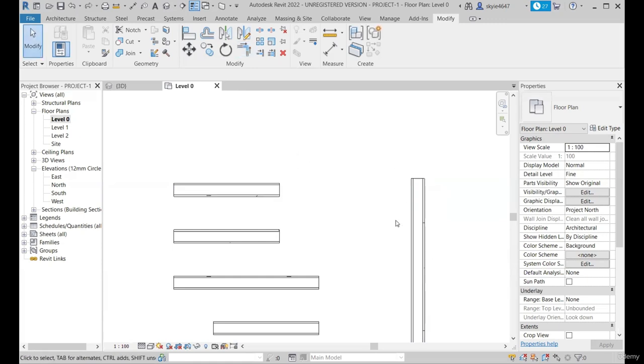So if I select the second element, you can see the corner is trimmed like this. I Control Z it again, and I will just extend this wall further beyond. Using trim extend can be a bit confusing, because it depends on which side of the center line of the first element you select. If I choose this wall initially and hover my mouse over the upper part of this wall, which is above the center line of the selected wall, you can see the dotted line terminating wherever the selected wall's center line is. You can see it with the dotted preview.